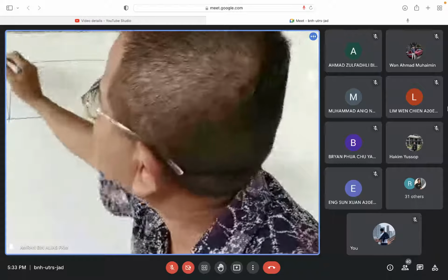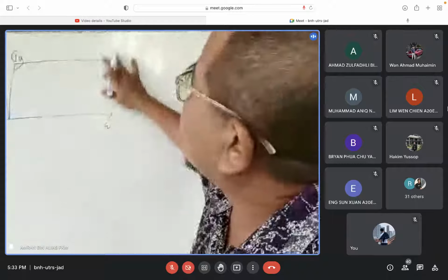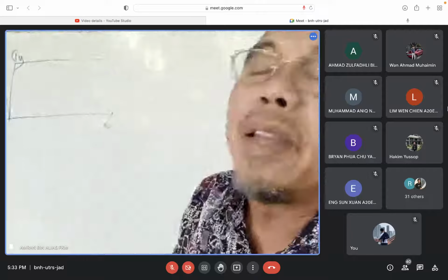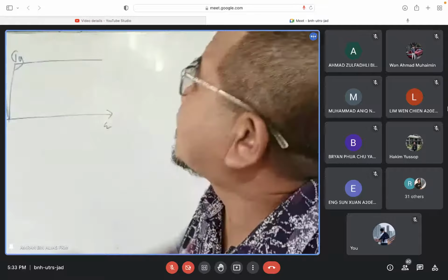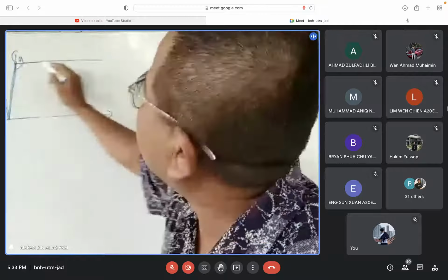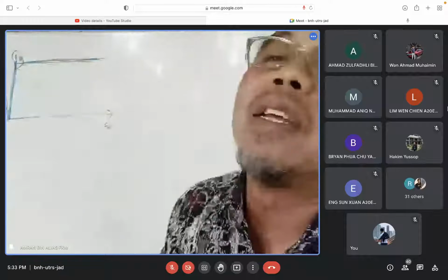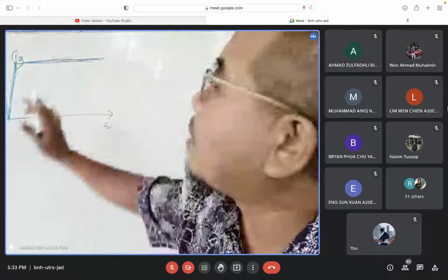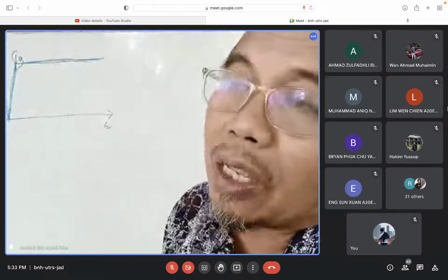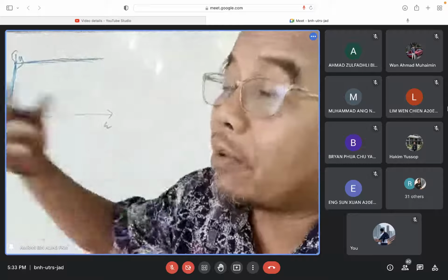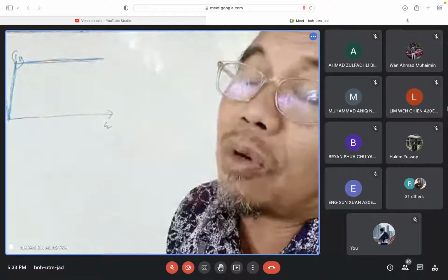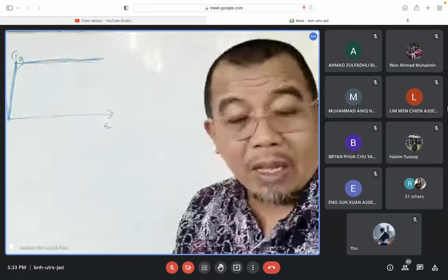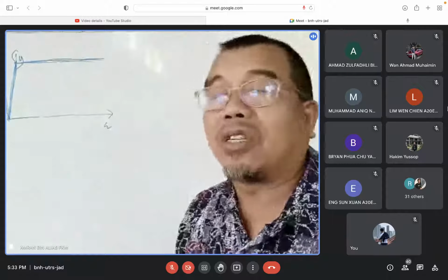The stress and strain. So this is the theory. The material behaves in elastic, perfectly plastic. Elastic here, and then perfectly plastic. That means constant plastic, sigma y. So those are the material behavior for our theory. So how can we go back to analyze how to calculate the work, how to calculate the force to make it bend.